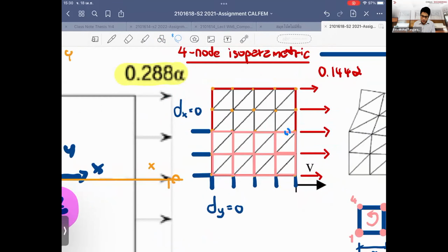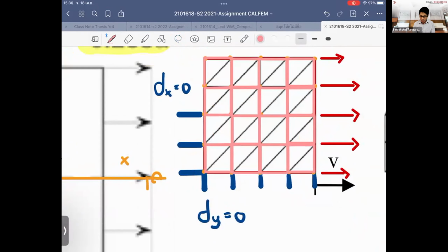So I keep doing this. And if I use a routine, I just put it into the computer and say, okay, we keep doing this for a repeating pattern, then I get all the mesh and the elements. When I have the mesh, I know exactly that this is element number 1, element number 2, element number 3, 4, right? I keep running the number. I know this is 5 up to 8. So you're seeing that you can use some simple calculation to tell the number of the elements and the connectivities, if you use the pattern that is repeating.